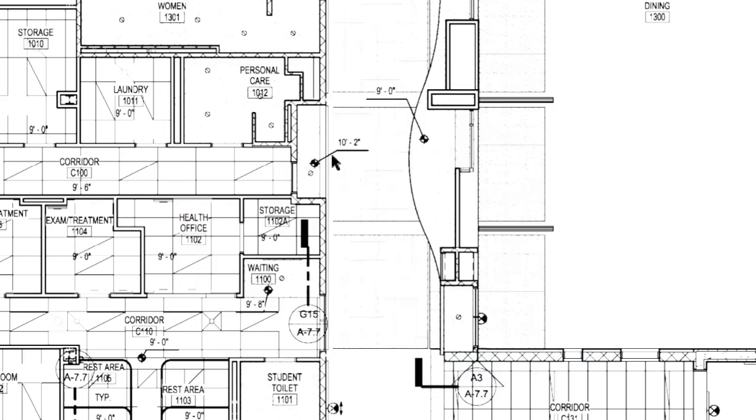And so right here you have a 10-foot 2 ceiling, and unless otherwise noted, this should be a 10-foot ceiling. So there's a 2-inch little wall bump up that takes this height up 2 inches. And then as you walk through this door, the ceiling height will drop down to what it says here, 9'6".